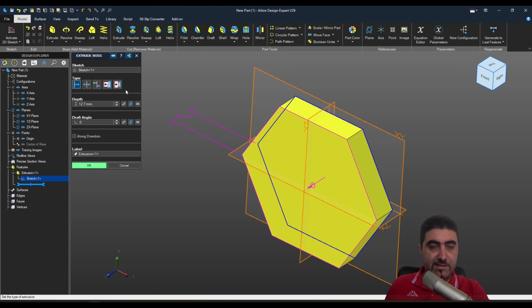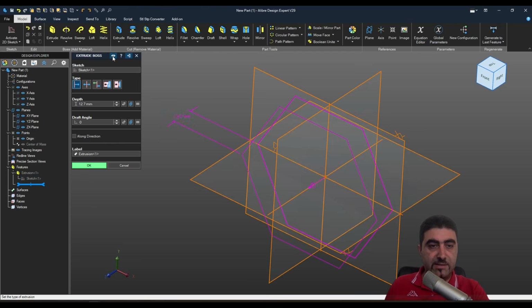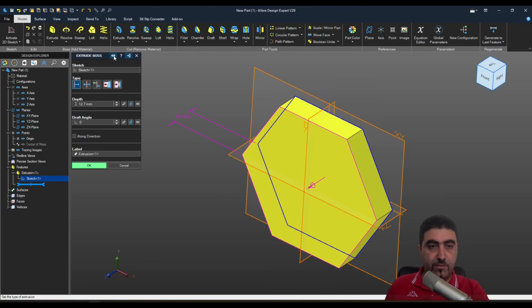And finally, the last thing I want to say about here is this is the toggle for the 3D preview, okay? And this is important because I want to make a demonstration, especially in the fill-in in Chamfer. This is an issue, and it's been an issue since V24, since I first got Alibre, and you actually resolve it just by clicking here and toggling the 3D preview.